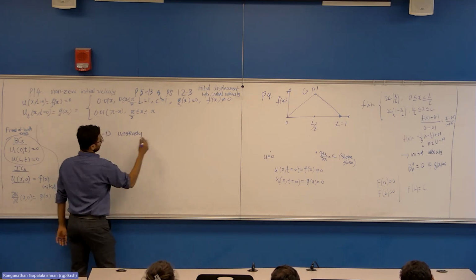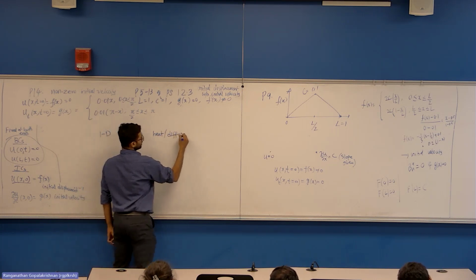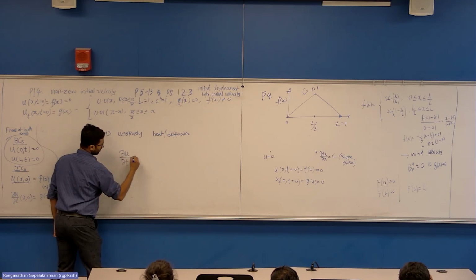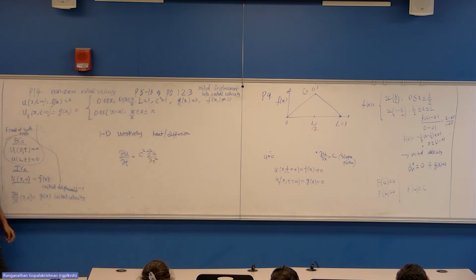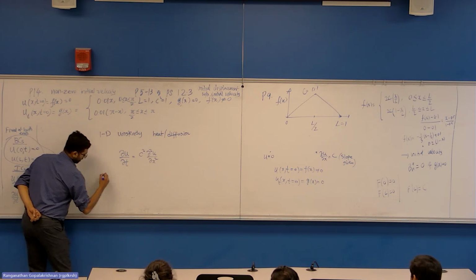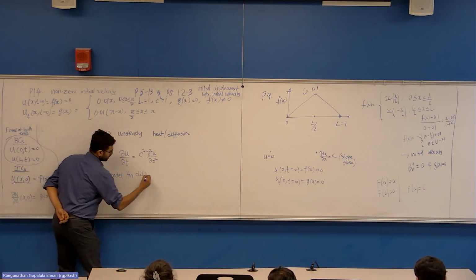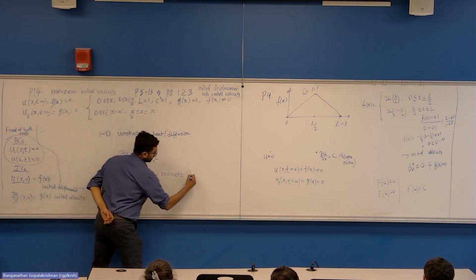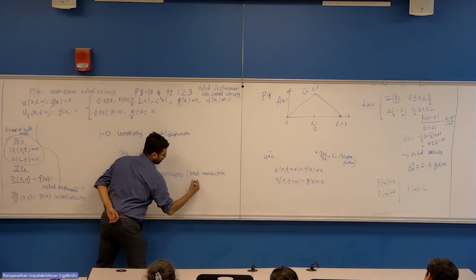Okay. The 1D unsteady heat or diffusion equation, that's what the usual name is, which is written as partial derivative with respect to time equal to c squared times the second derivative with respect to space. I'm not going into the derivation of these, but I'll just mention it is a model for diffusive processes like heat conduction or mass transfer.